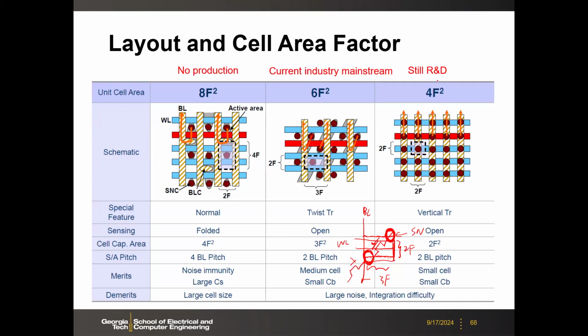So here, you have a question? The reason you have two word lines across the active area is because the middle node is being shared. That's the contact. First of all, word line is metal. You mean we have two word lines? Across the diagonal active region, you have two word lines. So there are two cells here. They share the same bit line, but you have two word lines. As I said, you have two cells. They share the same bit line contact.